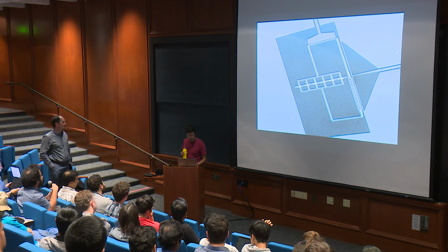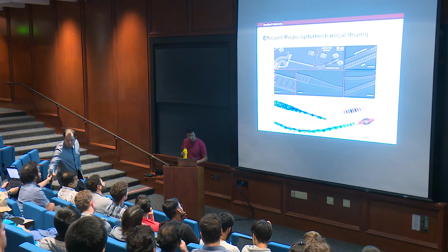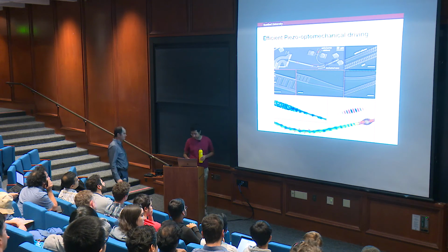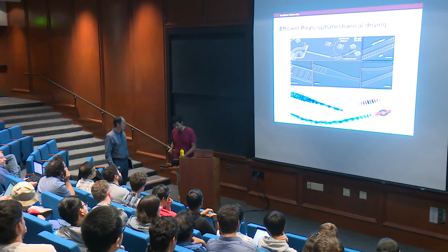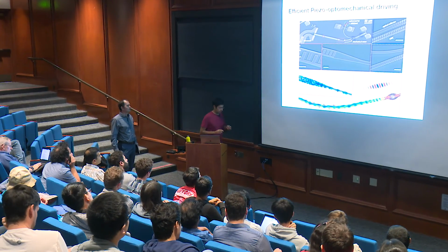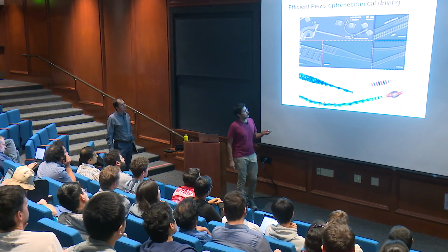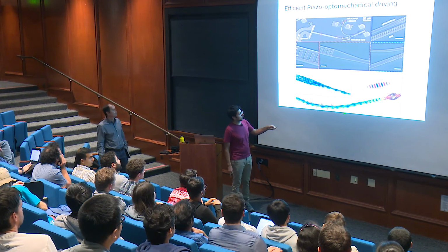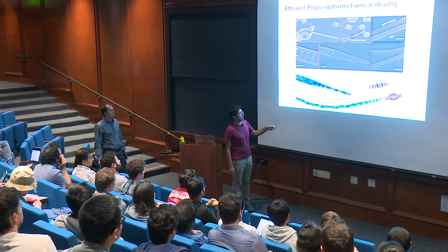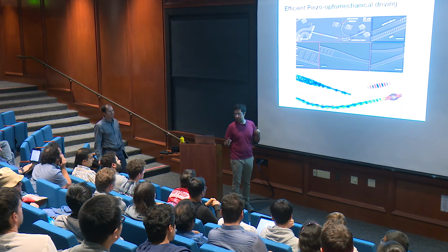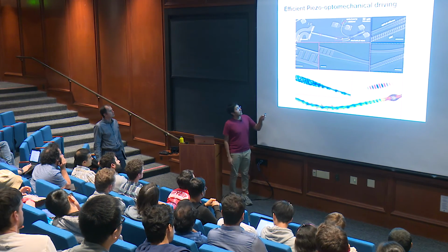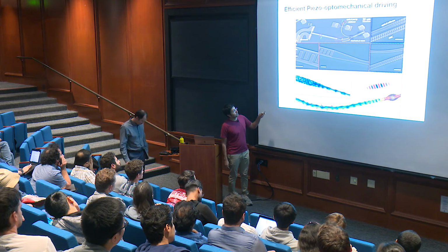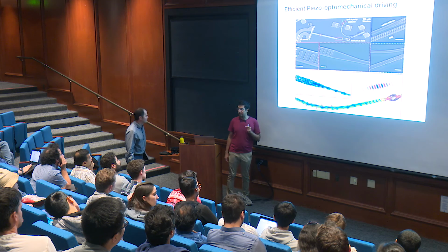Yeah, that's a great question. I think you could be asking one of two things. One is, what about higher order modes of this waveguide? And the other is, what about standing waves within this waveguide? If this electrode transducer is matched to 50 ohms, then that shouldn't be a problem.